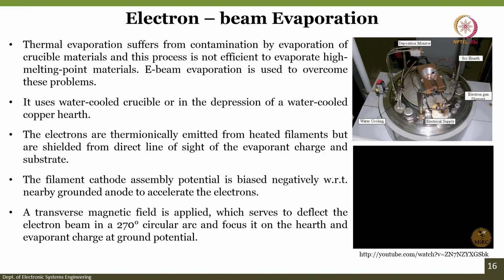So, this is a region where you can have your crucible, the electrical supply, electron filament gun, wafer cooling, and deposition monitor. You can see the quartz crystal monitor, the deposition monitor. Generally the QCMs are present within the chamber so as to measure the deposition rate.